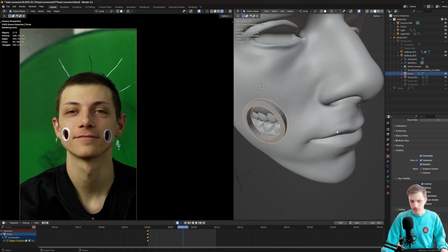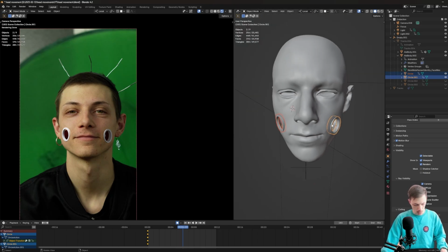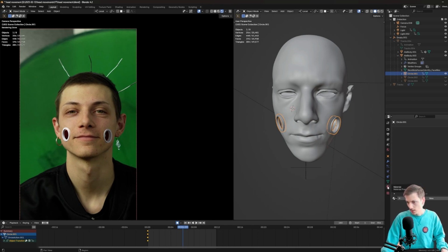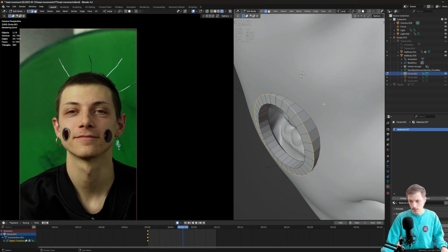Let's add a material to these two objects. We can join them. We click both, Ctrl J. Now they are one single object. I'm gonna do here a bevel to select the whole line, Alt and click, Ctrl B, and we have this. We can increase the number of subdivisions with the mouse wheel.